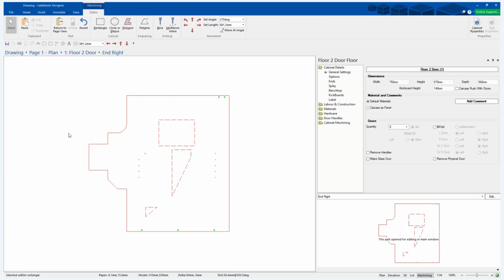So the machine editor is very powerful. We did have a different editor before where a lot of people said it was much easier. You could only edit the holes ultimately. So I just want to move a hole. The difference is the previous old editor that was actually happening in the cabinet was only modifying the DXF, the final output. This is actually editing the part in CabMaster, not just the DXF it's outputting. So this is much more powerful in here.